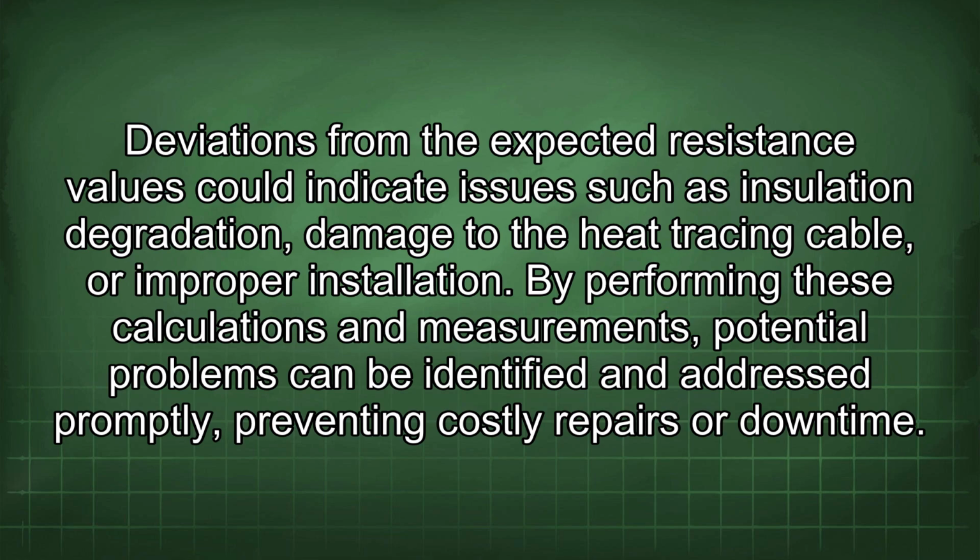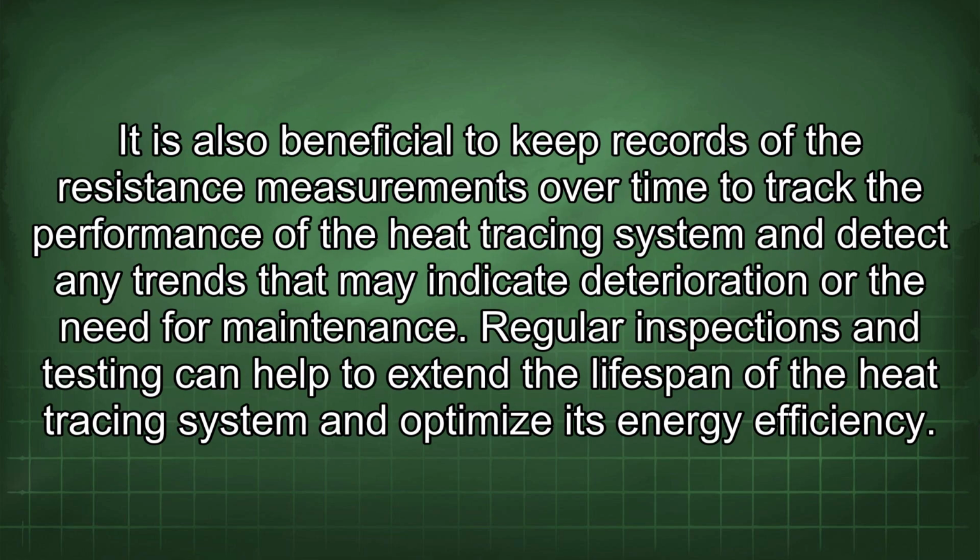It is also beneficial to keep records of the resistance measurements over time to track the performance of the heat tracing system and detect any trends that may indicate deterioration or the need for maintenance. Regular inspections and testing can help to extend the lifespan of the heat tracing system and optimize its energy efficiency.